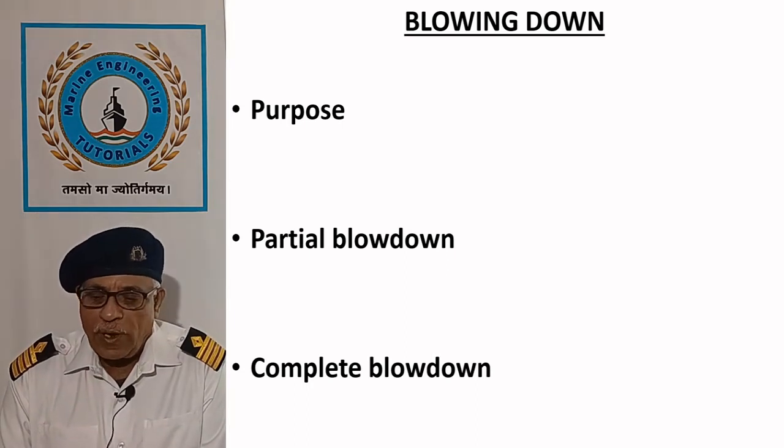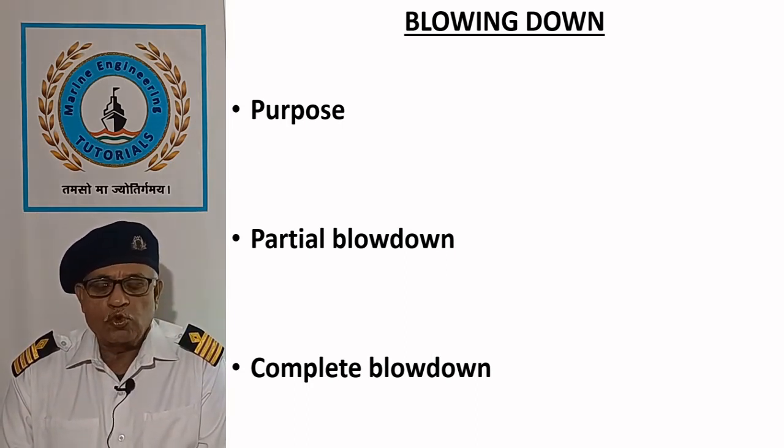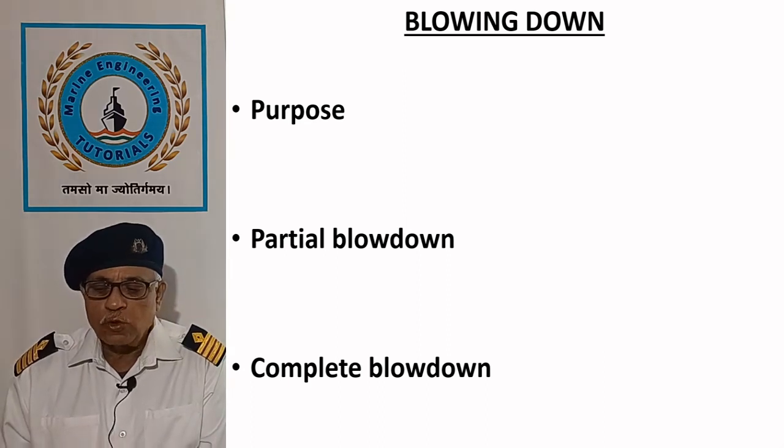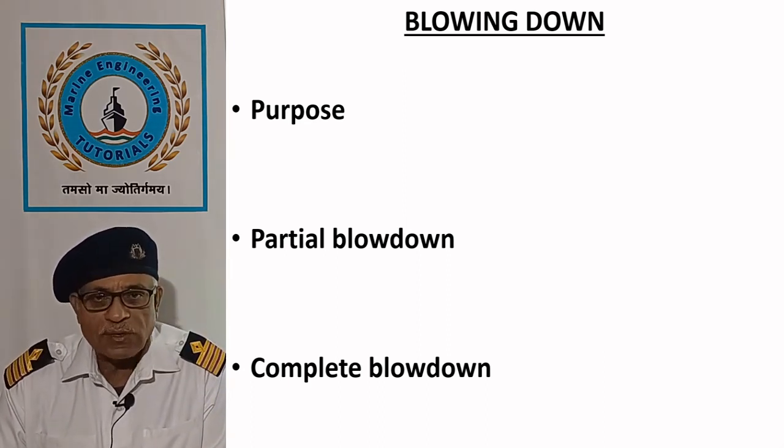After stopping the boiler, when pressure drops to 2 bar, the air vent is opened to prevent buildup of vacuum. When the boiler cools down, blowdown valves are opened.